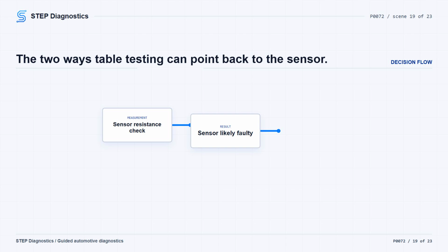F/9720 ohms, 30 degrees C/86 degrees F/7780 ohms, 35 degrees C/95 degrees F/6370 ohms, 40 degrees C/104 degrees F/5200 ohms, and 150 degrees C/302 degrees F/181 ohms. If the reading matches the table during harness side simulation, or if the sensor resistance is not in range of the table,